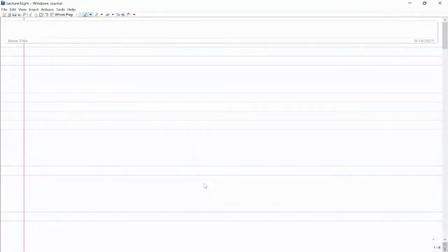Yeah, so rotation about the x axis is basically minus theta y, and then the corresponding W is going to be proportional to the y coordinate. So I would have written it in terms of the y coordinate, and similarly when there is a rotation about the y axis, that unit rotation will lead to displacement which is proportional to the x coordinate. Okay. Yeah.